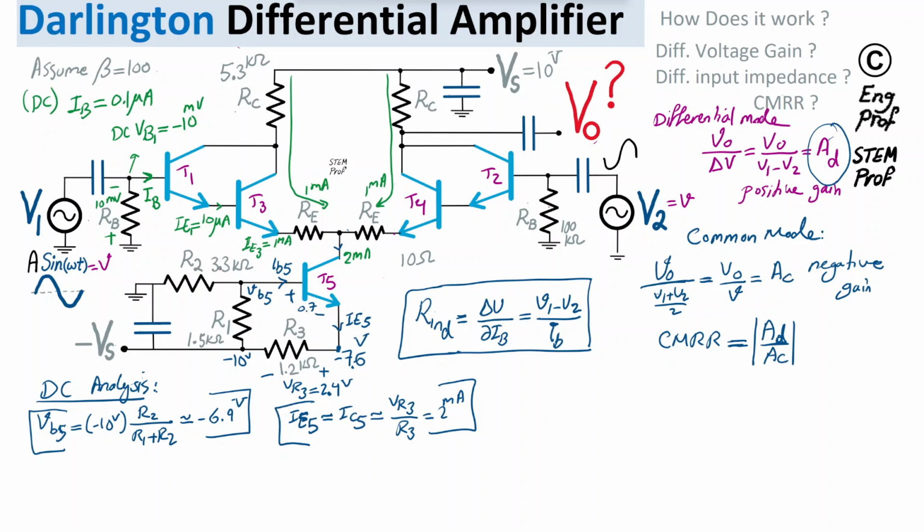Okay, so on top of that, what I see in the circuit is a plus minus VBE of 0.7 volt, and then another VBE of 0.7 volt. So from negative 10 millivolt, I have a 1.4 drop. So here it is negative 1.41 volt.